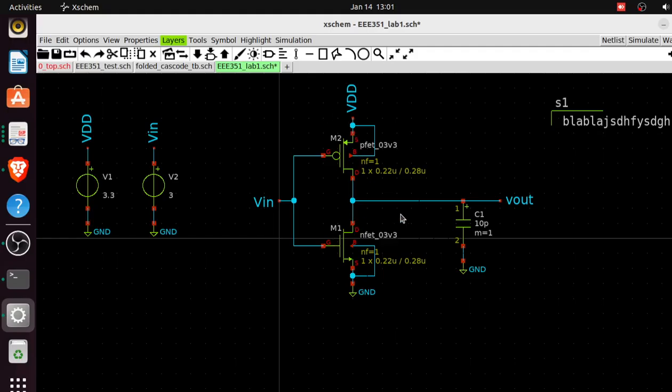So what you need to do is to make the width of the PMOS wider, so that it will be able to operate at the same capacity. Or better still, you can make the length of the gate of the NMOS longer, so that you want the NMOS to be slower, so that it can match the slowness of the PMOS. So either would work, but what we'll be working with is varying the width, not the length, because many times the length specifies the process node.